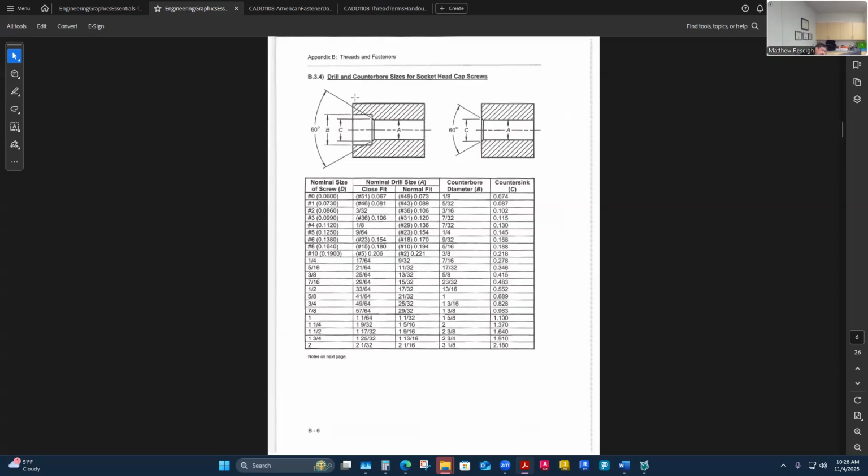And this is really common in automotive. You'd see this a lot as a way to sink the fastener down into the material, so I don't have a protruding head. And I feel like a lot of the reasons I would use this one is that the torque load they can handle is much more than maybe a countersink, which does the same thing.